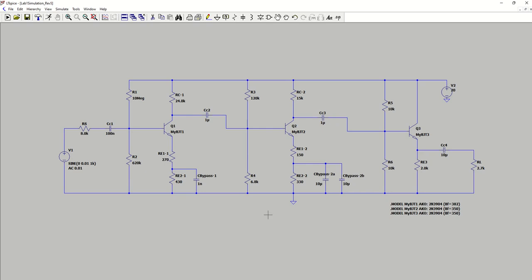So looking at our circuit, the circuit that we've been using for these lectures and tutorial videos is a single supply, right? So 20 volts at VCC, and VEE is tied to ground. So one way that we can do the power supply rejection ratio is just by varying this between 19 and 20 and seeing the change in the output for the two values of the power supply voltage.